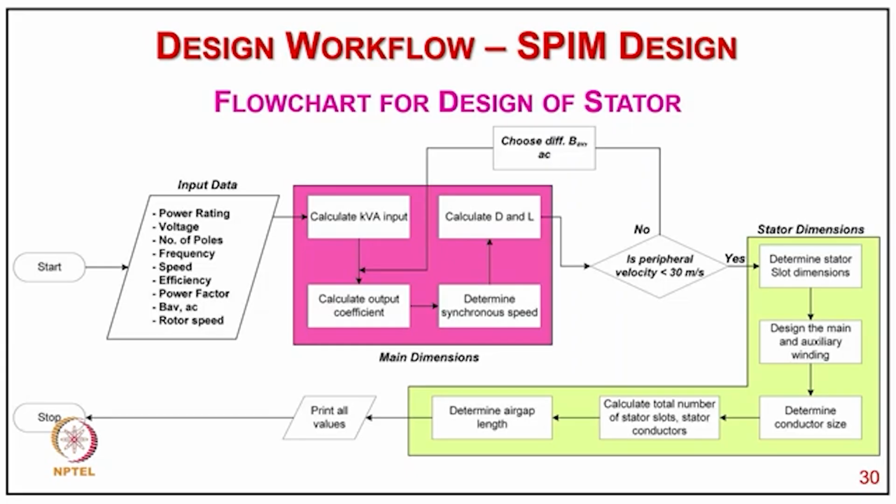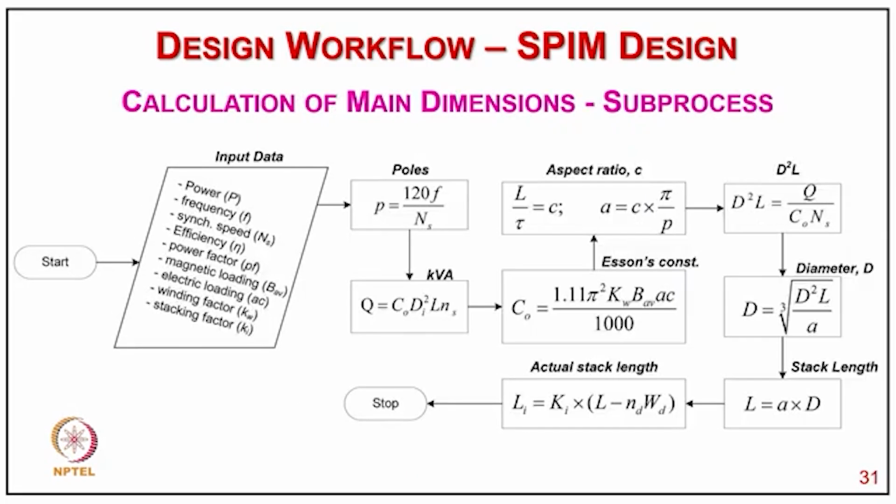If yes, determine the stator slot dimension, design the main and auxiliary windings, determine the conductor size, calculate the total number of stator slots and stator conductors, design the air gap length and print the values. This constitutes the design of the stator.